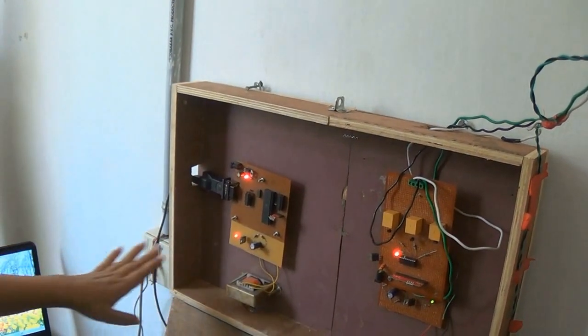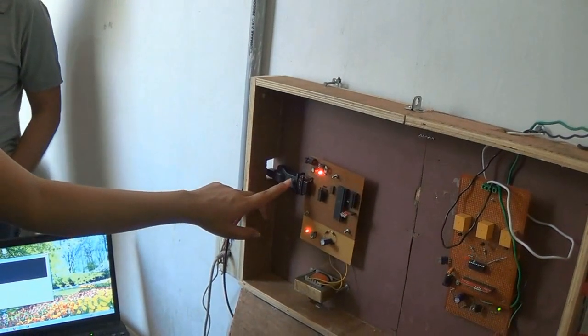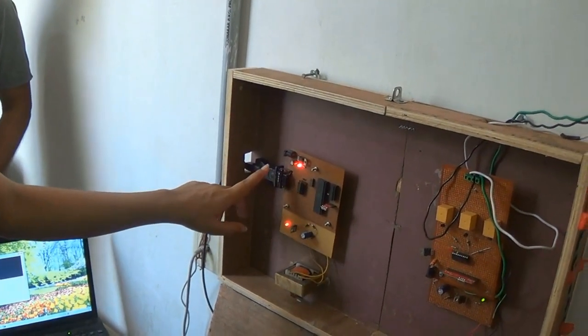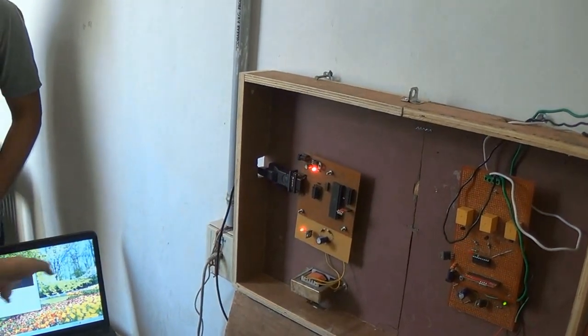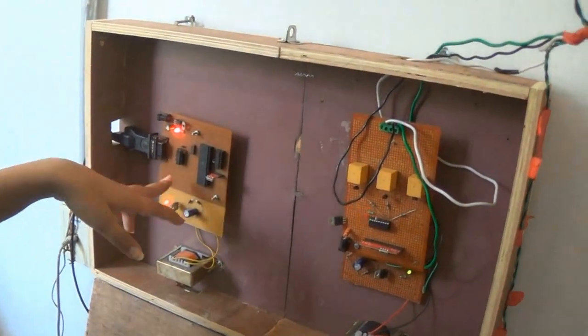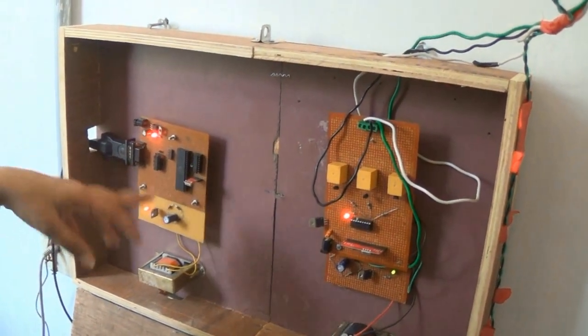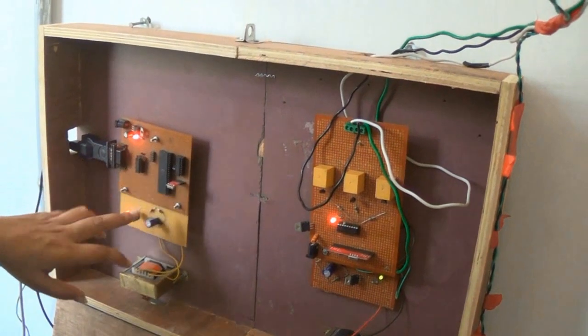In the transmitter part, when the instructions are given from the PC, they are received by the RS-232. It acts as an interface between the computer and the peripheral devices, and further the instructions go to the encoder, where they are encoded in a particular format. Then the instructions are received in the microprocessor.